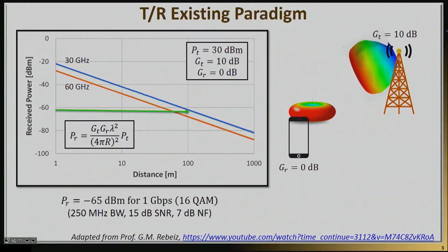So I've actually plotted here an interesting scenario based on the Friis transmission formula we've seen in this class, where on the vertical axis is the power received, and the horizontal axis is distance. And I'm using, again, the very simple ideal model, the Friis transmission equation, and some realistic or semi-realistic assumptions. I'm assuming that the transmitted power here is basically 1 watt.